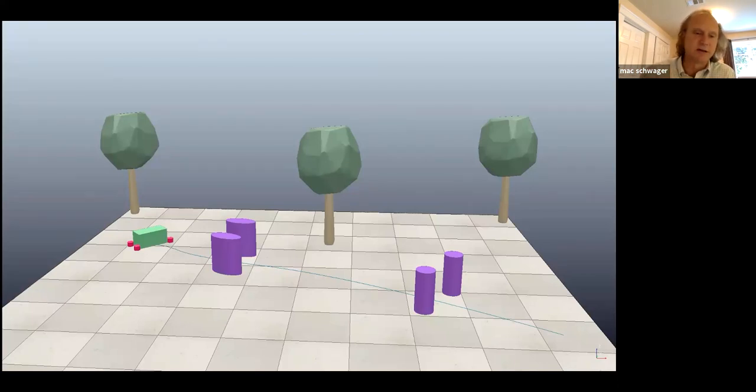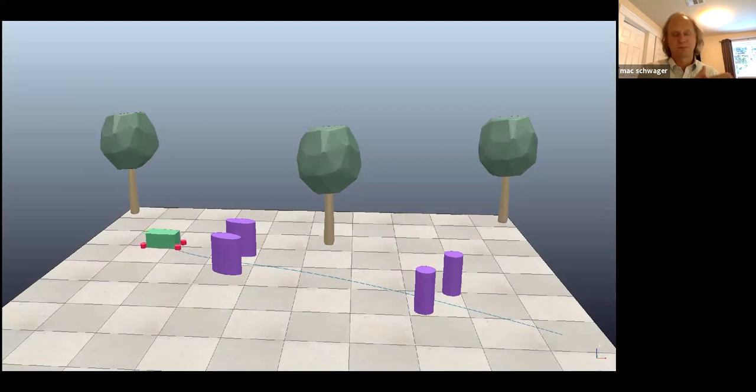Those are entirely hidden from robot I. And robot I is responsible for avoiding collisions with those obstacles that it can sense. And you can see we apply this in a receding horizon fashion. The robots plan over maybe a 2-second horizon, and then execute for a little while, and then replan and execute for a little while. And this is the resulting behavior.